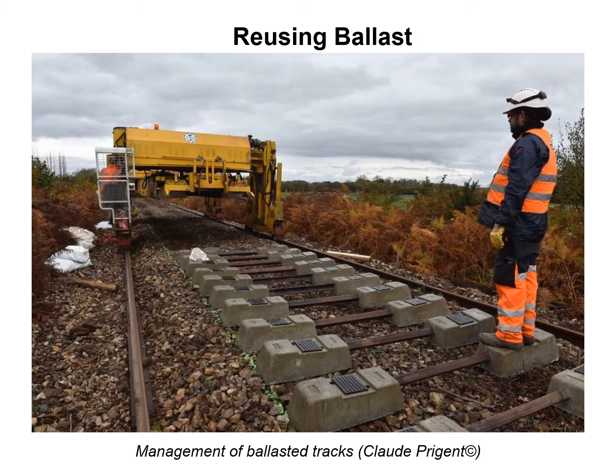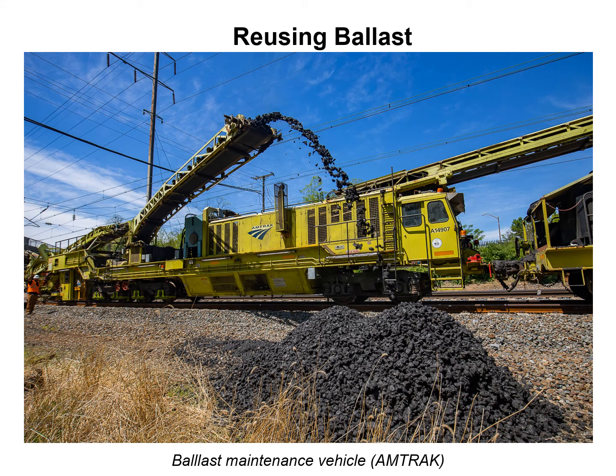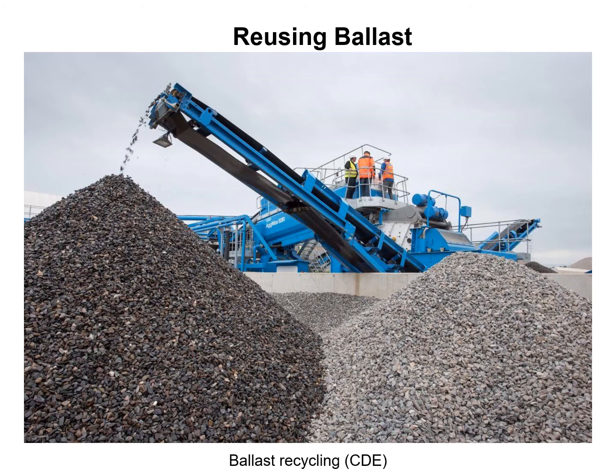One way to manage the ensuing deterioration of ballast is to detect when a limit of grain breakage or abrasion is exceeded and go through the process of cleaning the ballast. This process consists of getting rid of particles that no longer match the required criteria, such as size and angularity. Grains that fail to pass are then recycled and revalorized for use in other structures.